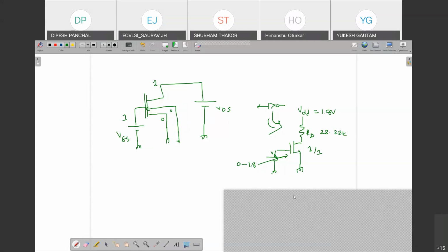Sir, in this, first you have to write the number and then the value, or first the value and then the number? Suppose first M1, then 2 1 0 0. Sir, that I wrote, but in the second line, suppose I have to give the value to VDD. So for VDD, what do I have to write? VDD, let's say it is between here. You have to give the number also. Let's say it is 3. So between 3 and 0 you have VDD, 1.8.